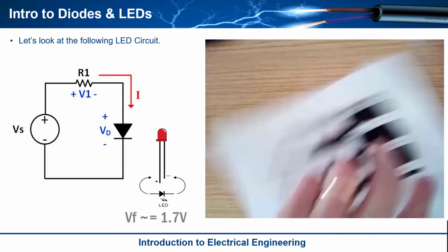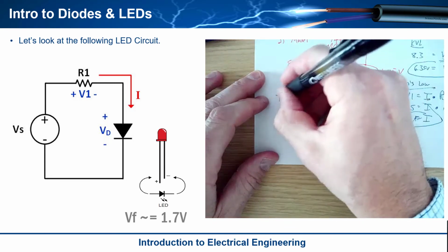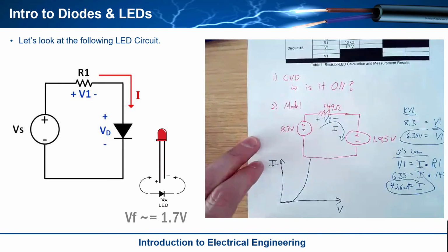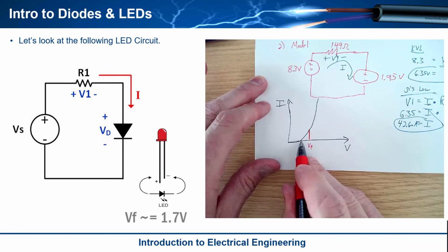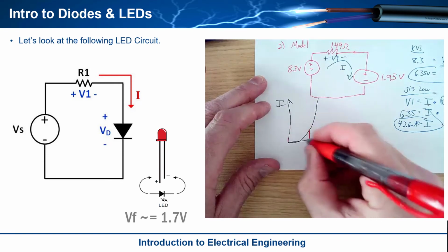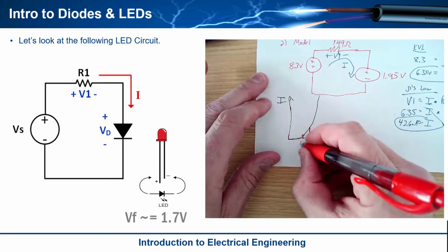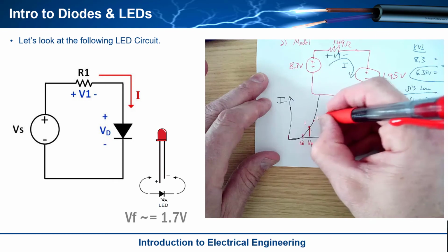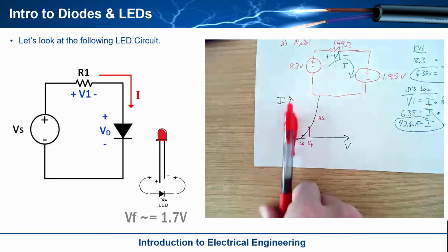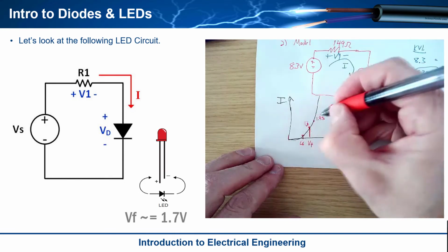Well, it turns out that that's just how diodes are. If you remember the IV curve, as you put a voltage across it and you look at the I, it goes like this, right? And what you're thinking about here is as the current is lower, the forward voltage is basically just this knee right here. And if the current is smaller, what you're seeing is this right here. So this was like the 1.6, and this was the big one, so it'd be like 1.95. The last one we just did was 1.6, 1.7, 1.95. So this was like 1.6 right here and then 1.95.